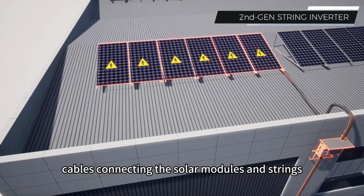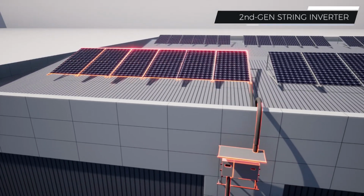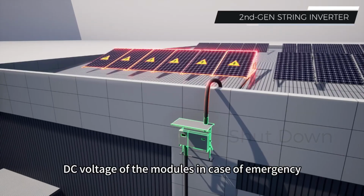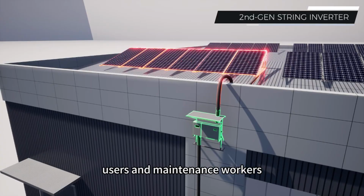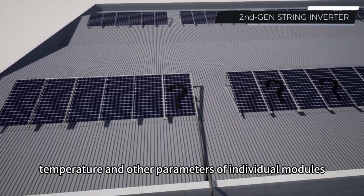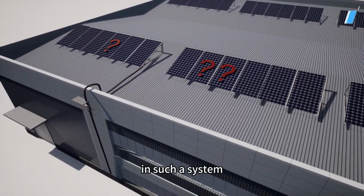Furthermore, the DC cables connecting the solar modules and strings carry a high voltage of several hundred volts during power generation. Second-generation inverters are unable to effectively shut down the high DC voltage of the modules in case of emergency, leaving serious safety risks to system users and maintenance workers. Second-generation systems also cannot monitor the power output, temperature, and other parameters of individual modules. Therefore, module-level failures cannot be remotely diagnosed in such a system.